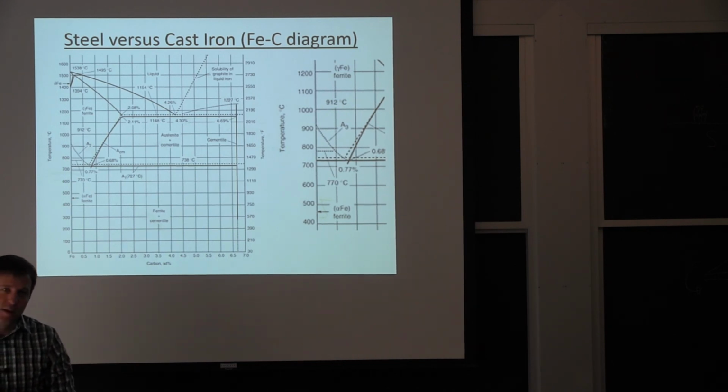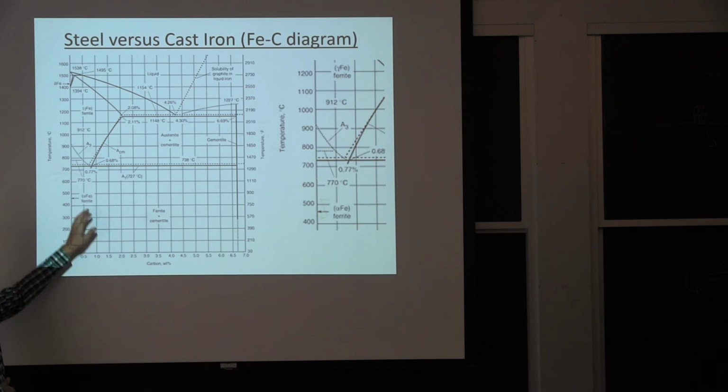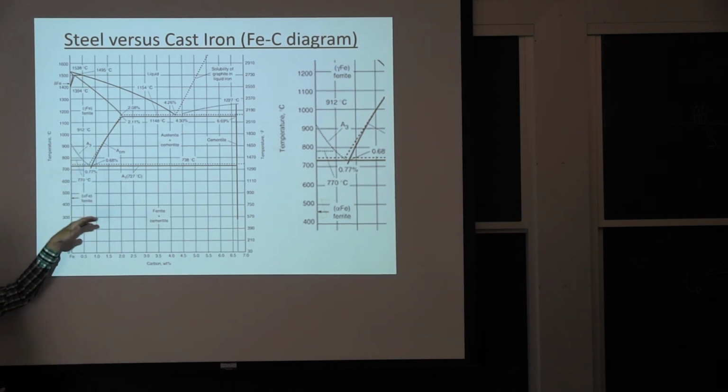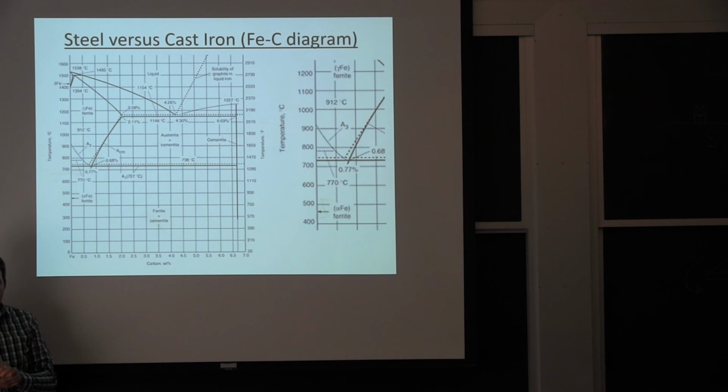Well, to some extent it's associated here, because if I'm going from the austenite here, the single phase, to that phase that's not in the phase diagram, it's the martensite. It's a tetragonal structure. It's not as deformable as these cubes that I circulated yesterday. If you do that, you get a volume increase of about 4%. So that's another reason for getting distortion.